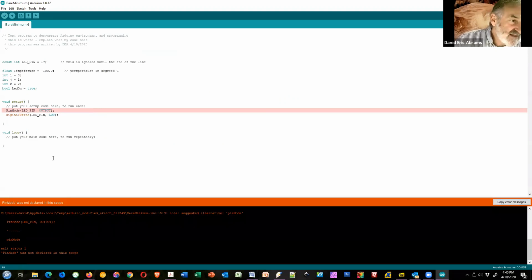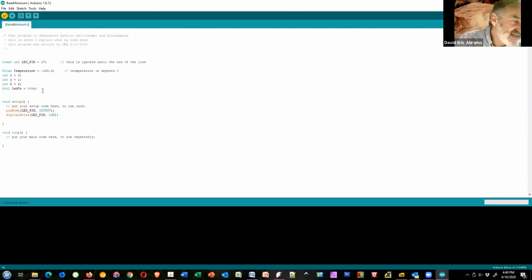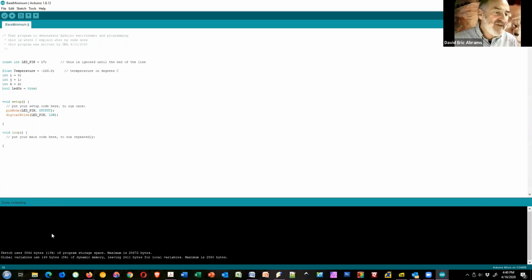PinMode was not declared. Why is it unhappy? It's a lowercase p. That's what I mean about case sensitive. You will be very confused unless you realize that it's case sensitive. All right? Oh, it's happy. All I got was white.